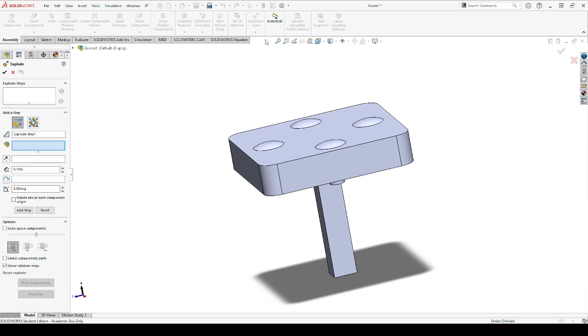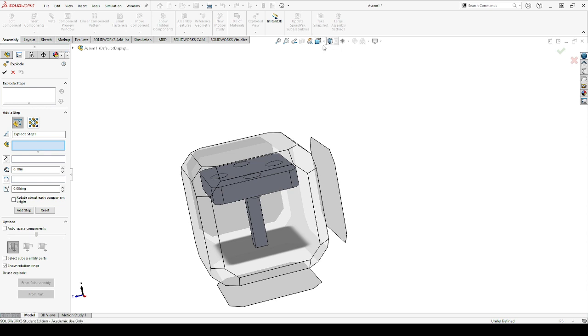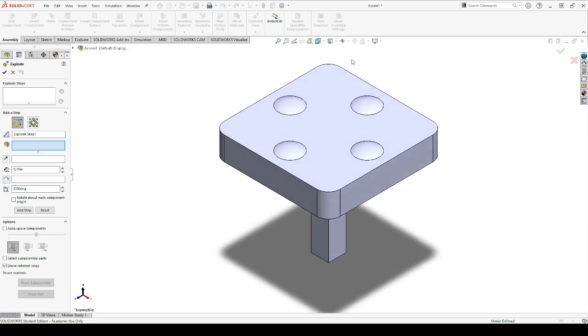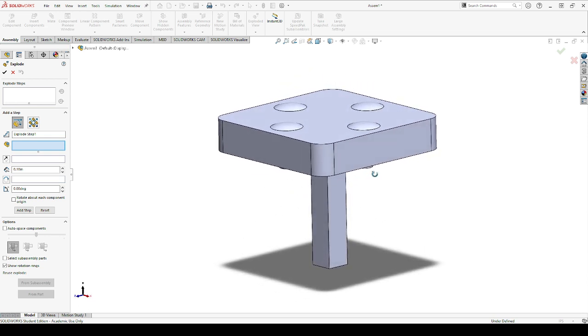And the way the exploded view works is that you're going to take all of our parts and pieces of our assembly and basically move them away from each other. The main thing is just making sure that you can actually see visibly all of your different parts. It doesn't have to be too perfect or anything like that, but just make sure you're able to see it. I like to keep mine in the isometric view as much as I can, which I believe is this one, isometric. Probably going to rotate it down a little bit, that way we can see a little bit more.